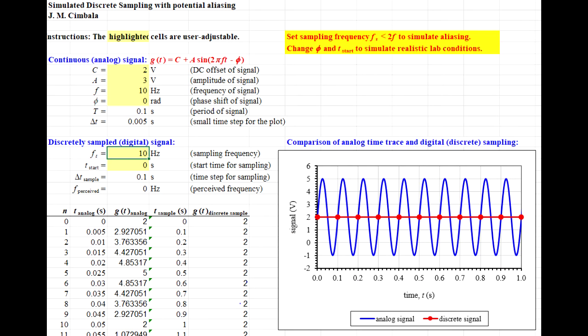Aliasing in terms of data acquisition and sampling is the misidentification of a signal frequency, which as a result will introduce errors and an incorrect frequency. Aliasing will occur when the sample frequency is lower than double the signal frequency.